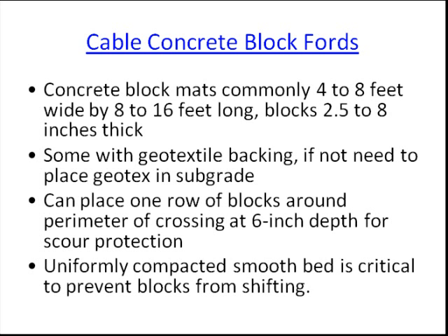Unless the subgrade is uniform, smooth, and well compacted, the blocks can shift over time. Each block is independent of its neighboring blocks and can settle, rotate, or tilt. If this occurs, it can result in damage to the mats and a rough driving surface that may be dangerous to livestock. Once the blocks start to move, scour can endanger the longevity of the crossing. So, subgrade preparation is a key element of crossing longevity for cable concrete fords.